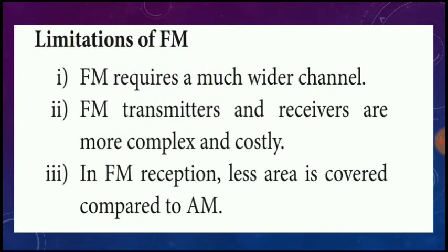Yes, limitations of FM. So this is a 2 mark question. FM requires a much wider channel. FM transmitters and receivers are more complex and costly, and in FM reception, less area is covered compared to AM. Right?